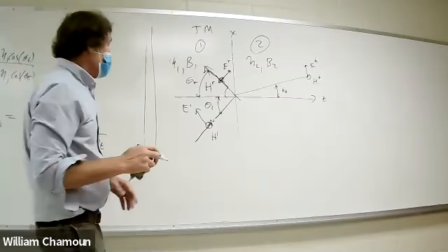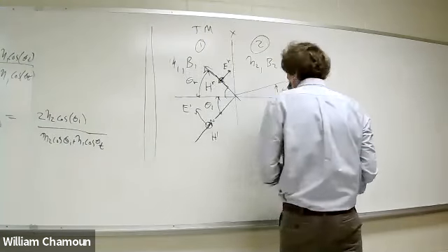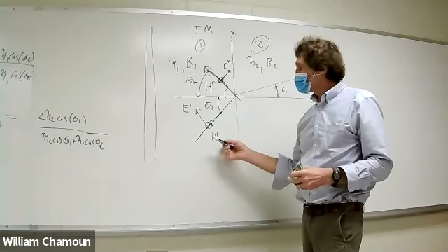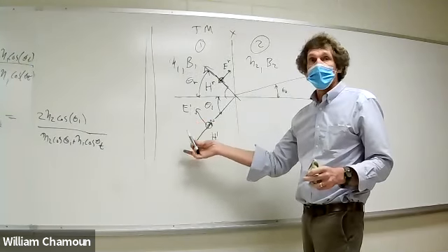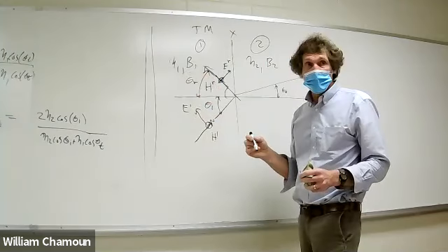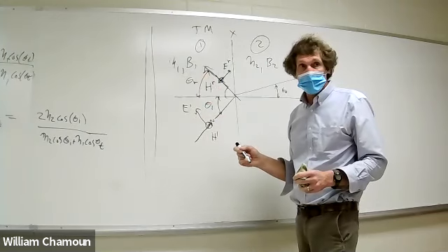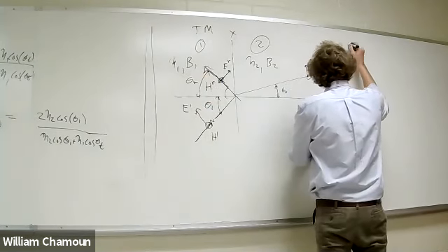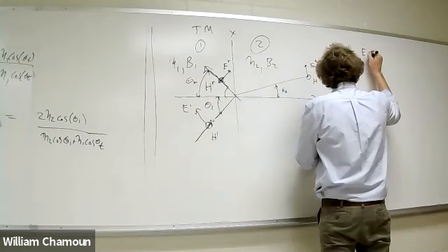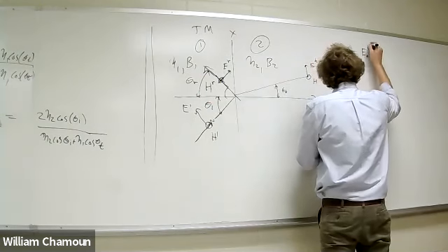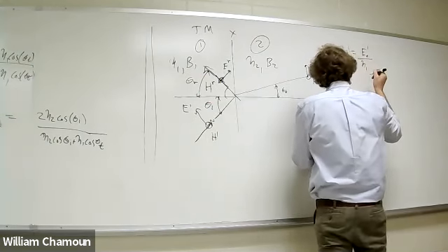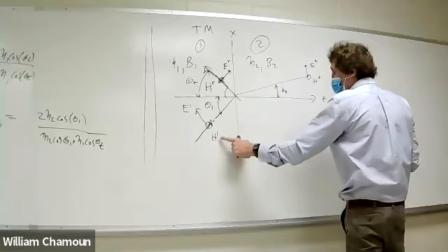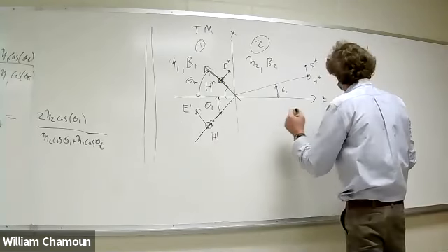Okay. All right, so now for this one, I'll just tell you what happened. The H field incident will have the ratio of E incident over the intrinsic impedance, eta 1, which will give me the H field. Do you all agree with that, class? I can go ahead and say H incident will be E naught incident over eta 1. Now, when I take a look at this, the orientation of this thing right here is going to be in the a_y direction.